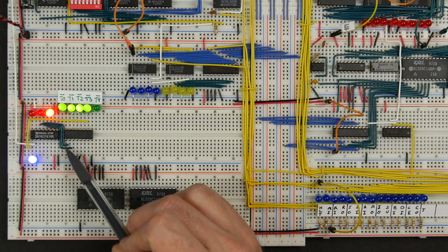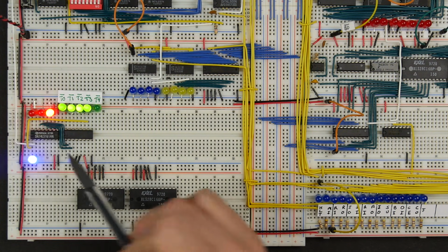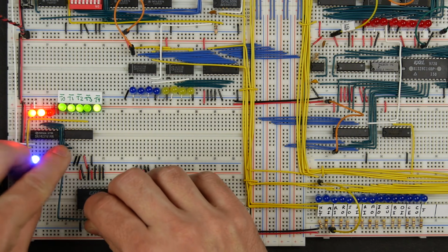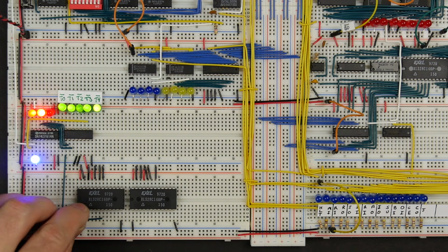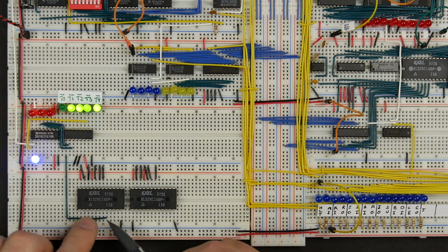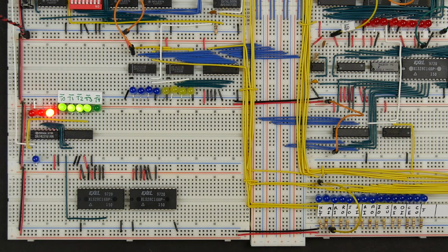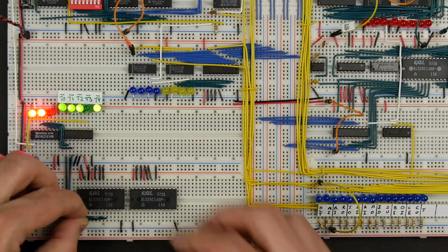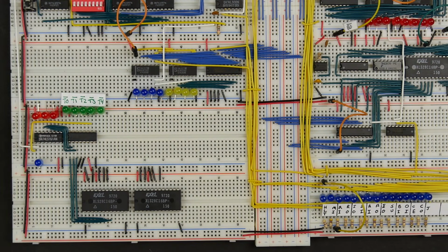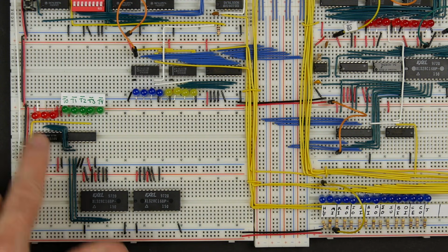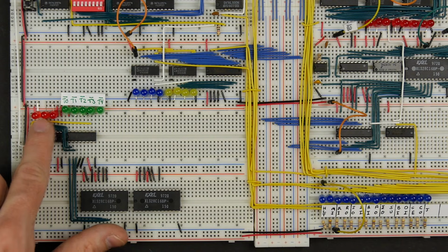So you can see this LED here on the left is the least significant bit, and that snakes around here, so that's this signal here. So if I hook that signal there to address 0, which, let's see, these 3 pins here are going to be the I/O pins, so that should be A0 there. And then this next one is A1 and A2. So there we go. I'll just disconnect that.